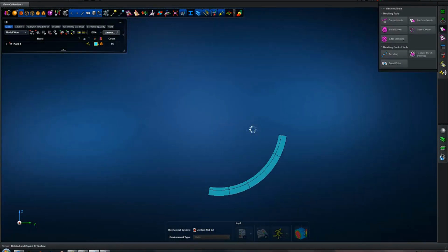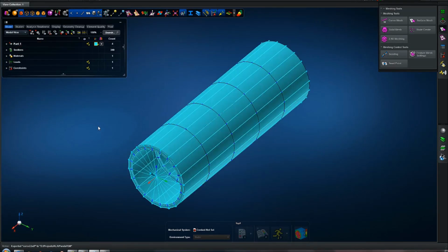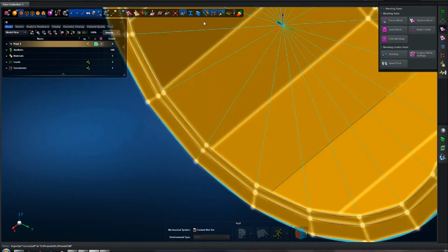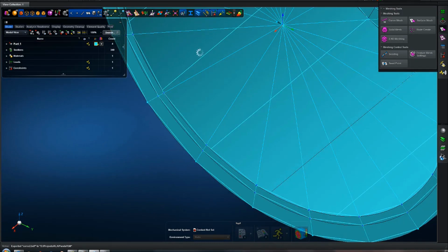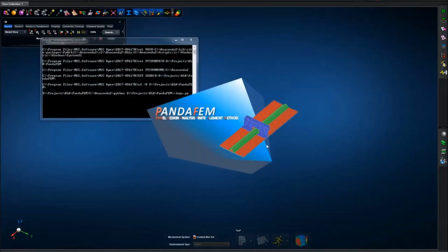First of all, we're going to look at a parametric automated fuselage build process. You can see in the bottom left-hand corner some of the scripts that run through. So the tubular section with shells and 1D bar elements is defined. Turning the beam display on, we can see how those stiffeners have been generated, and we've got some load application at either end of the structure.